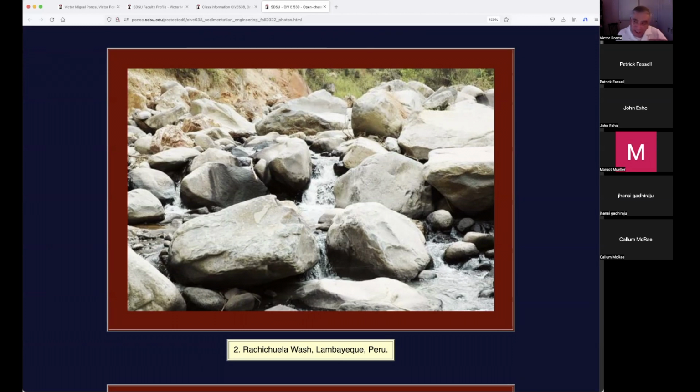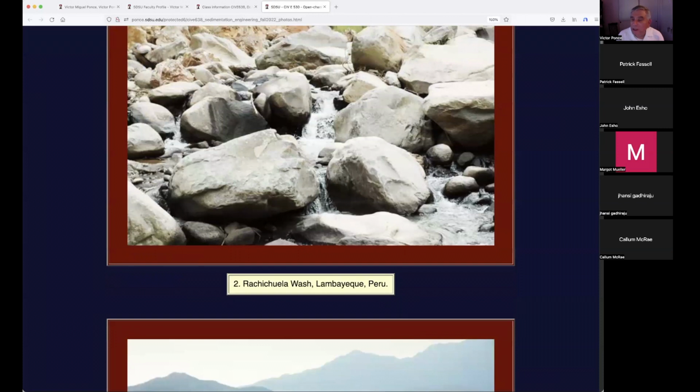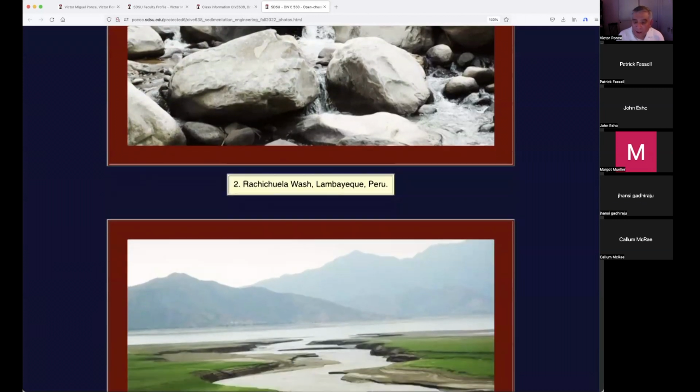So as you can see, this is the beginning of our understanding of why we are studying this. For one thing, the friction. For another thing, the stages, the calculation. This is a tough calculation. What Manning are you going to use in there? That's a tough question. What Froude number is it? We don't know. That depends on where you are within the cross section, right? So as you can see, the difficulties of having to deal with these real world, real life situations.